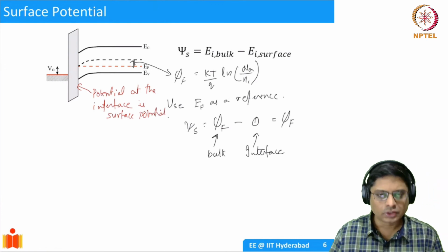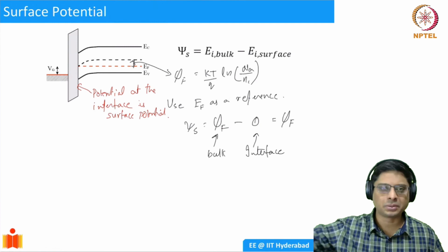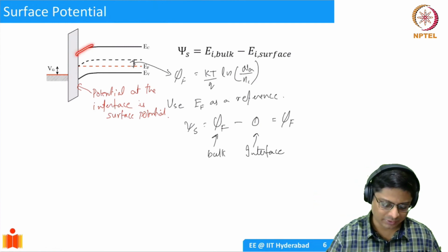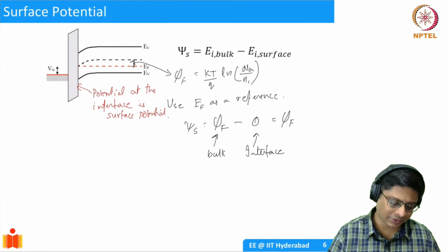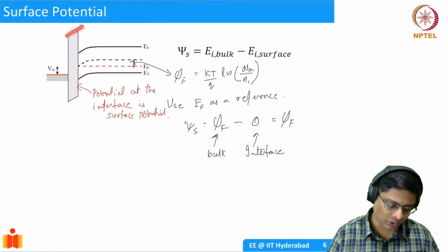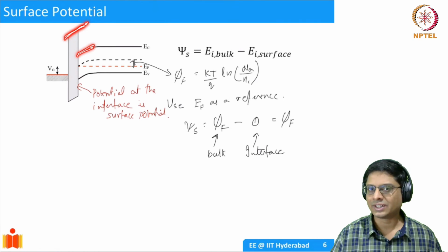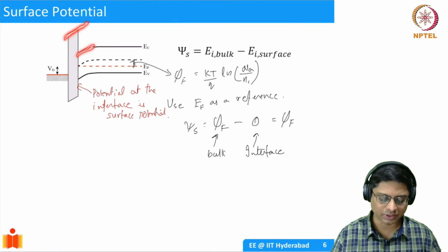Essentially, you have a positive surface potential, and then 0 potential in the bulk. So the electric field is positive, and your bands are nicely bending upwards, which is consistent. Once you have this, your bands in the oxide are also going to be in the positive direction. Remember, these are always consistent, in the same direction, unless there is an interface charge, which changes this.